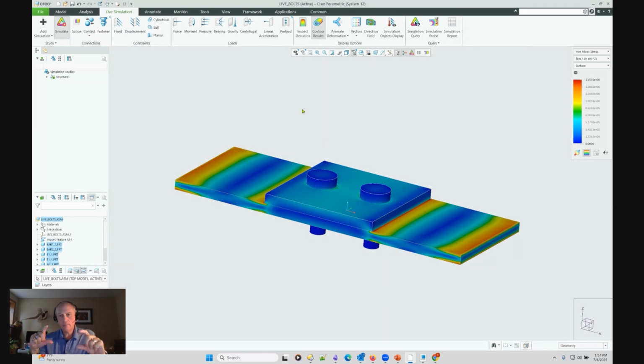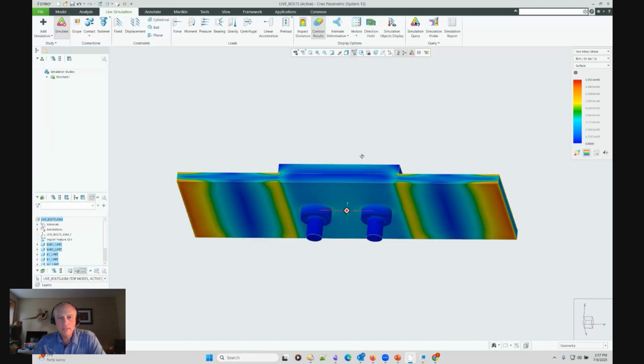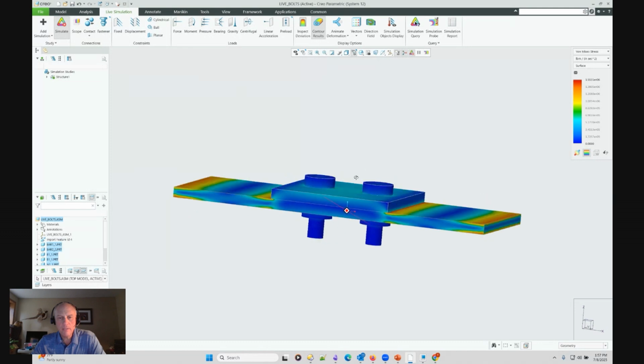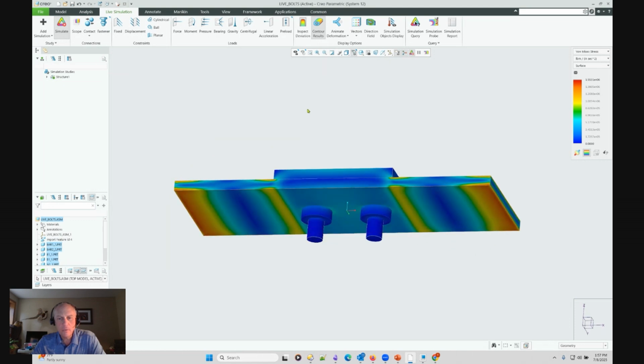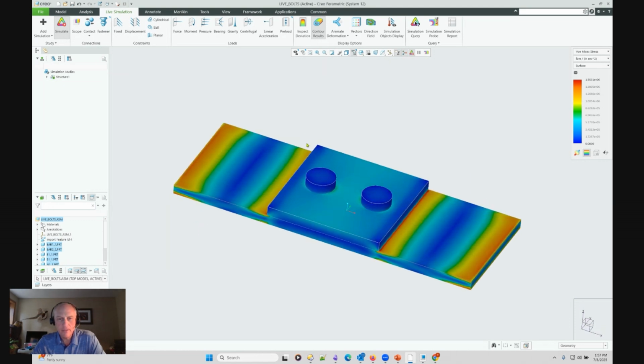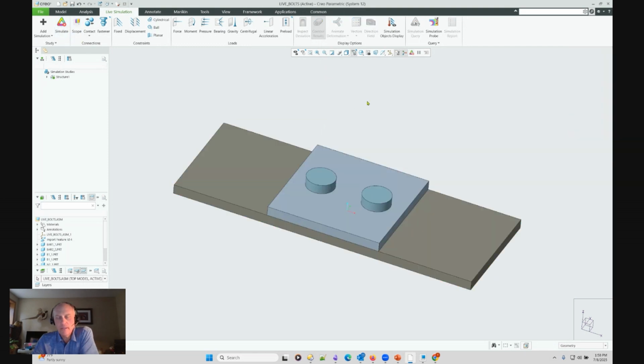as now things are actually going to be clamped together, and the contact interrelationship or interface between those components is now correctly captured. So now I can see that's what I should expect to see from that simulation, because the model is now actually tracking that contact or the relationship between those two bolts, the top plate, the bottom plate, and the little nut that's holding things, or rivet that's holding things together at the bottom. So that's some pretty cool stuff in the structural simulation that PTC's added with ANSYS in the newer versions of Creo Simulate Live.